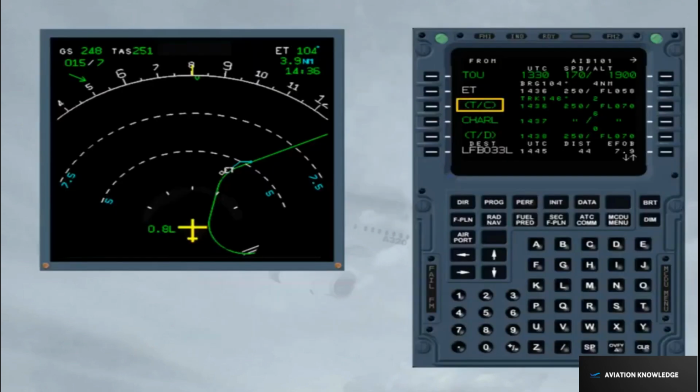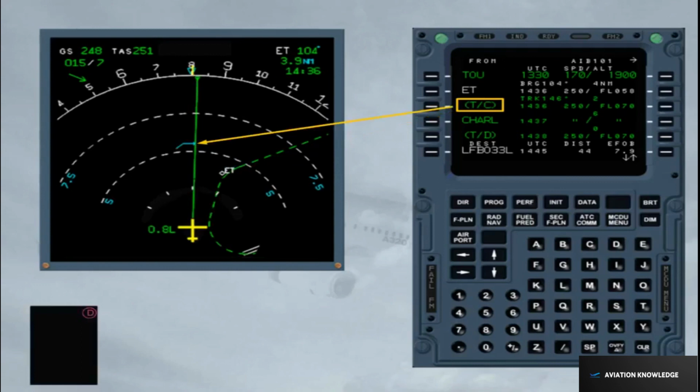Predictions are provided on navigation display by symbols in the current active autopilot modes. If navigation mode is active, they are displayed along the active flight plan. If heading track mode is active, they are displayed along the track line. Decel point. Altitude constraint, amber if predicted missed, white if disregarded. Speed change. Interception point of the descent profile. Top of climb, level off. Top of descent, start of climb.